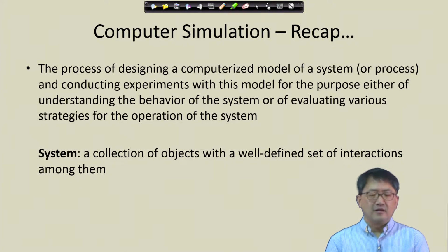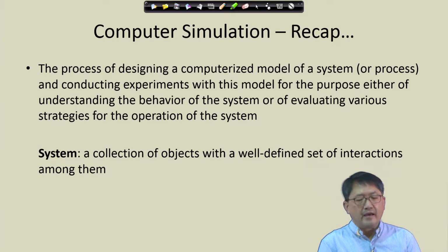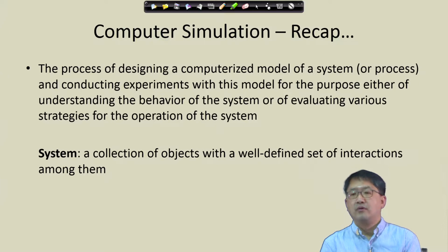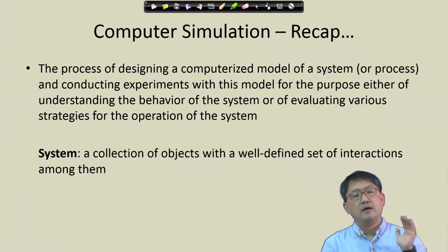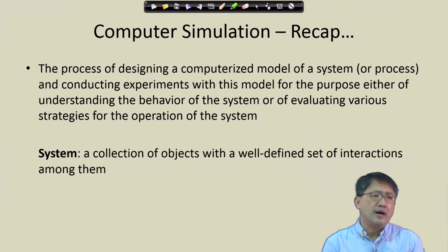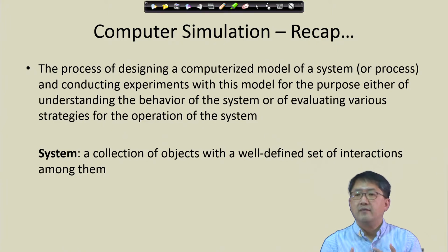In a nutshell, what we are doing in simulation is that we have multiple components. We'll get into the traffic simulation, but you need to model the roadway system, modeling curvature of the roadway, vertical and horizontal curves. You also need to model the control component. You could have a signal, stop sign, you could have a ramp metering. Those are different components. And also different types of vehicles with different physical capabilities. Smaller cars can probably go faster than heavy trucks at the beginning of starting up, things like that. So we gotta have these multiple components.